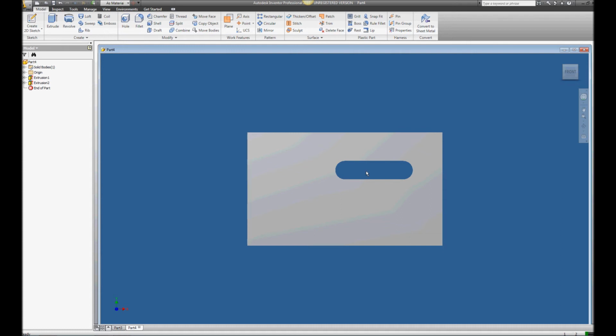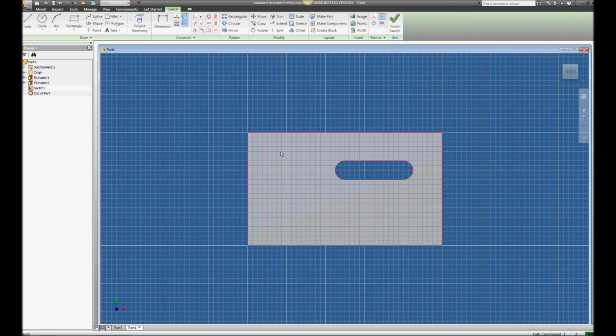Next step. We need to draw our hole. Leaving 3D, going 2D. Drop in our sketch plane, and we're off. We need to just make a circle. Does it matter where the circle goes? Not one bit. Does it matter how big it is? Nope. Right click, done. Alright. So, we need to make our hole with location. D10. We're on D10 right now. And it's telling us that it is 1/4 of the overall plate width.